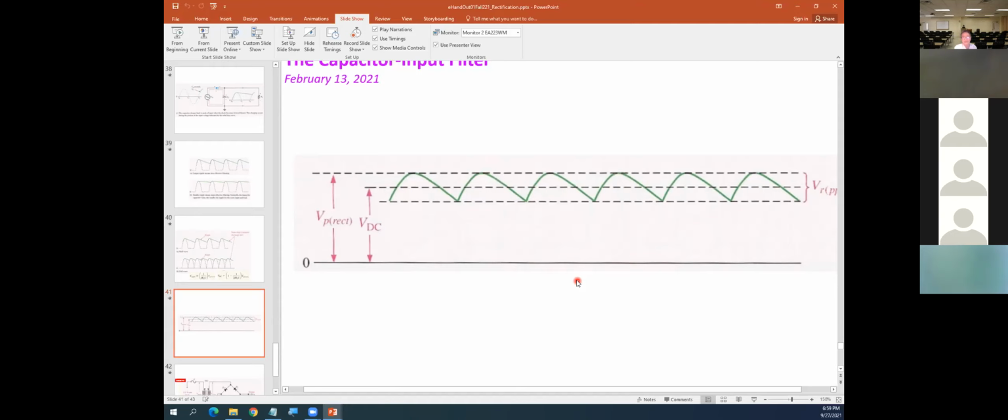When you're working on the circuitry to fix it, you run the program, they tell you to apply input and measure at the output. They want a sine wave, how many volts peak to peak, what frequency. That's what they already wanted. The only thing is you measure, and if you cannot get what they wanted, that means something must be wrong and you have to fix it.